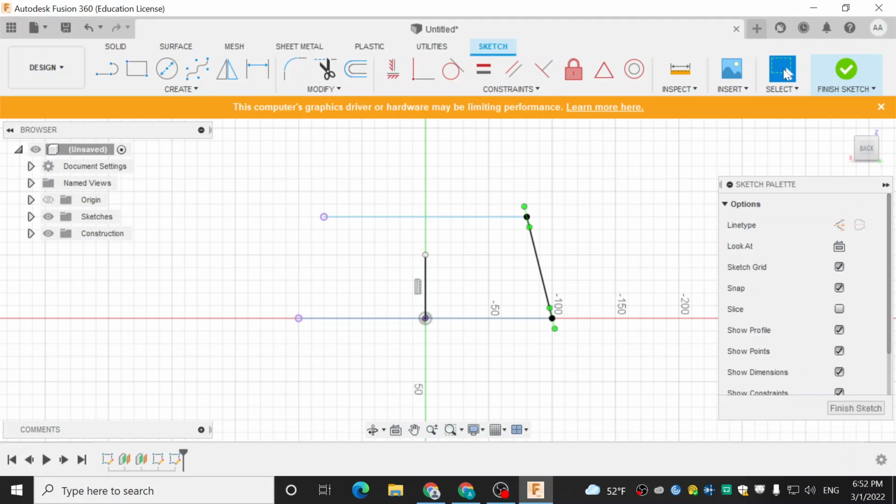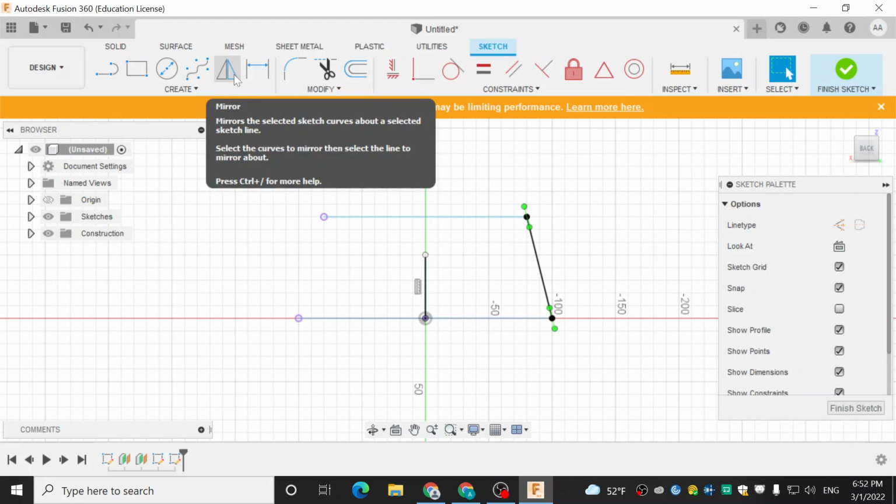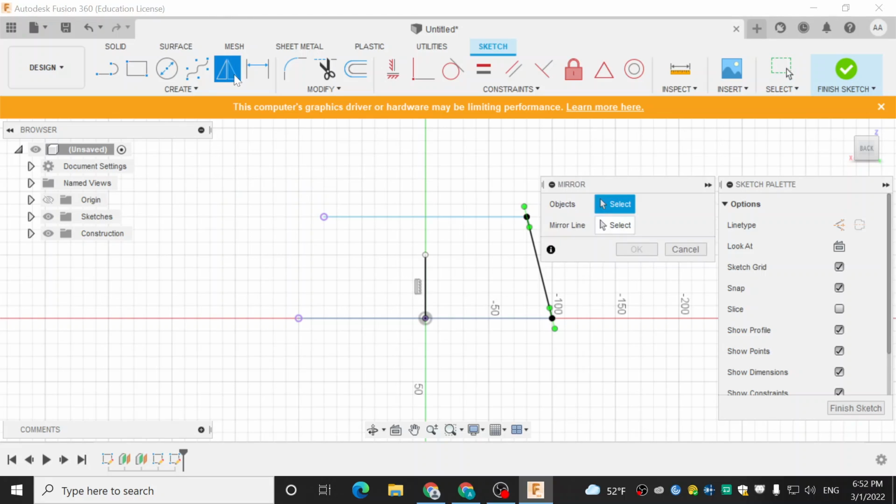And you'll notice that it's not connecting my 2 planes or anything like that. It's just a straight line in the middle of my page. So I will go to the mirror tool. I will select that, and I will select the spline line that we created previously.